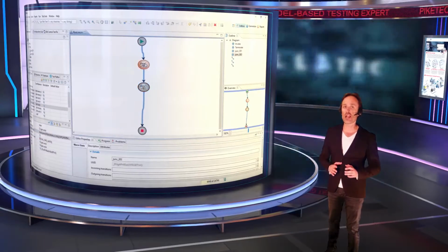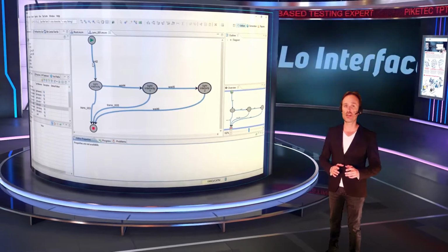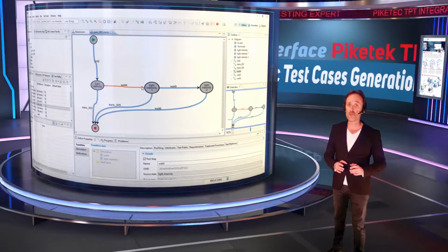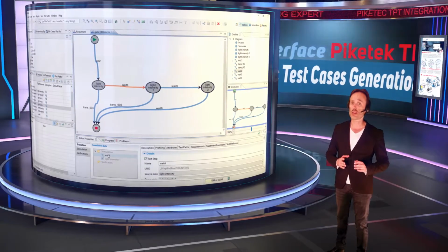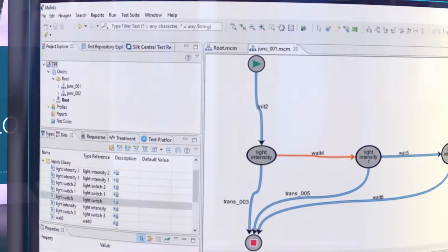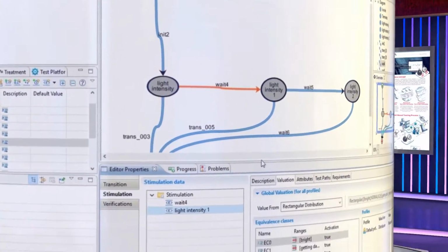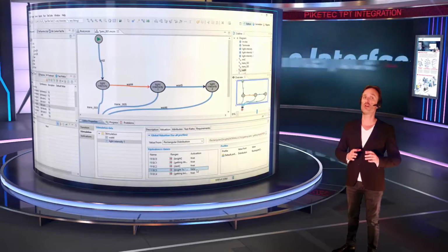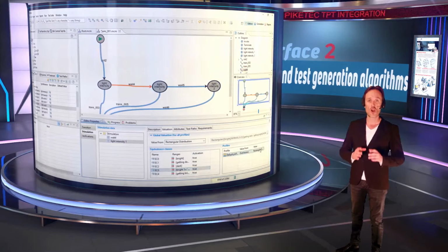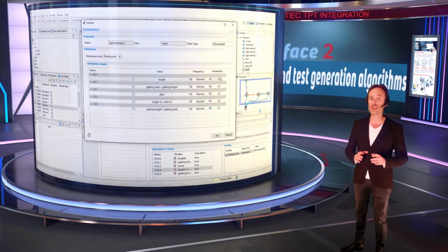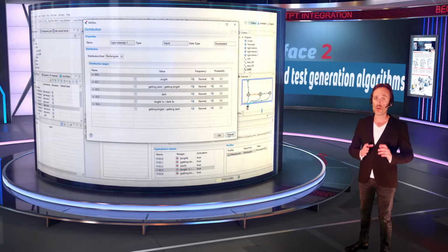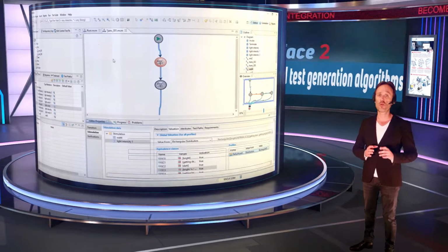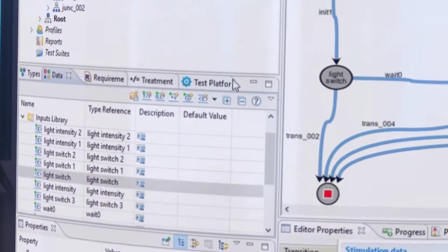All the TPT model has been automatically created in MaTeLo. The two parallel TPT processes have been transformed into two MaTeLo subchains. In each MaTeLo subchain, the same TPT state transition diagram has been automatically created. On each transition, enumerated inputs have been set with, by default, the equiprobable random selection of the TPT variant.